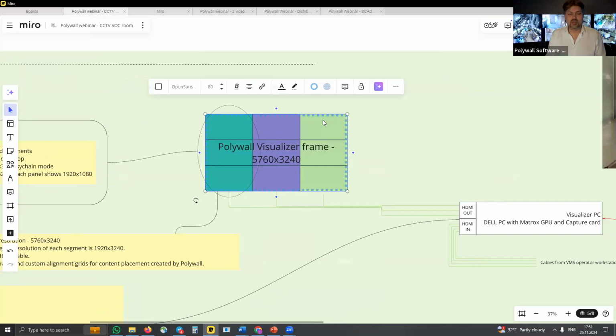It was an image across all the screens managed by Polywall. In general, this story of making the daisy chain is a very common way to decrease the workload and decrease the number of cables from the controller to your video wall. And by doing this, you decrease the requirements for the controller. You minimize the cost of it, keeping the resolution the same. So that is, again, a very common and important cost-saving option for your projects, to use daisy chaining.